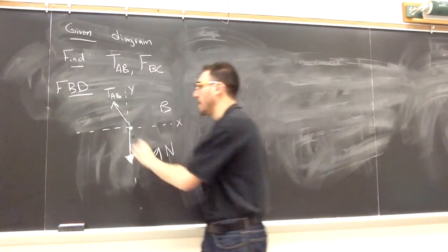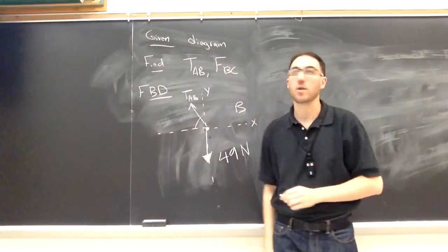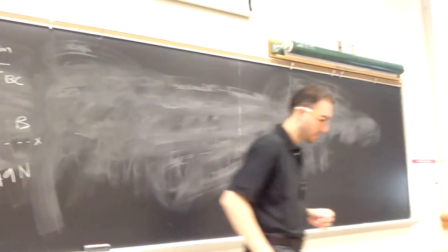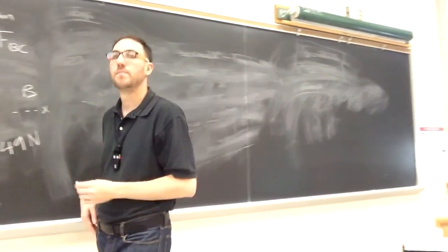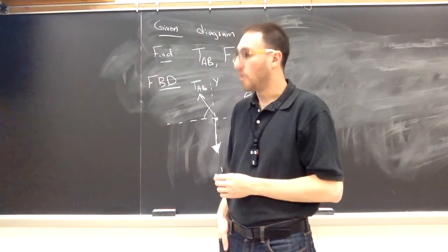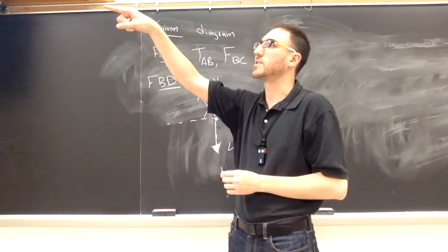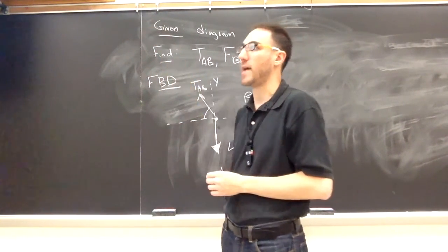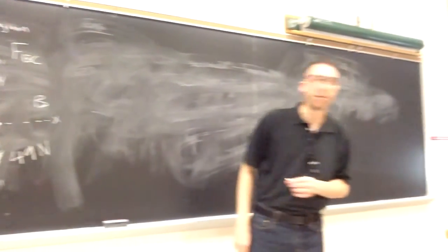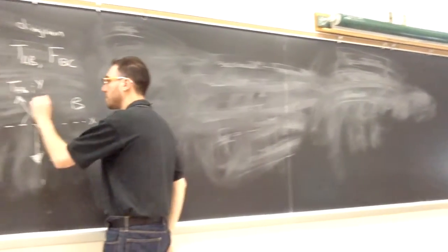How can we find at what angle that force acts? One way is the arctan of 150 over 80. That's probably the best way to find that angle, and it's going to be a 62-degree angle.